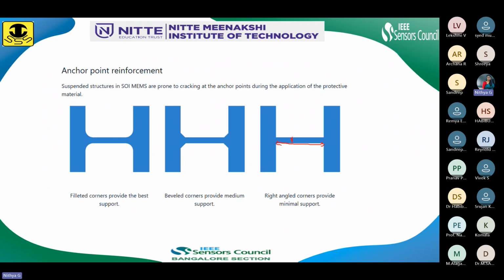Otherwise, there is a high chance that it would curl up, so it may not give the required results later on. So one thing to remember: whenever we have a beam, if its thickness is less than 6 micrometer, the maximum length I can have is 100 micrometer. Whereas if the beam thickness is less than 6 micrometer and it is anchored on both sides, then we can go up to 500 micrometer as the length of the beam.